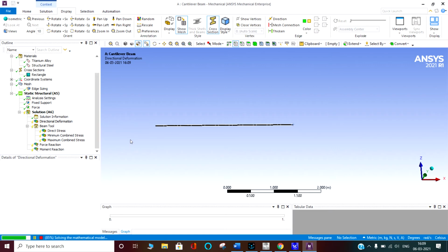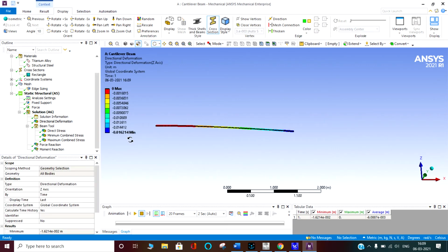First, it is discretizing the body into small elements that we have done by the meshing, and after that it is using the three-dimensional equilibrium equations. That is del sigma xx by del x plus del sigma xy by del y plus del sigma xz by del z plus body forces is equal to 0. So like that it is solving.